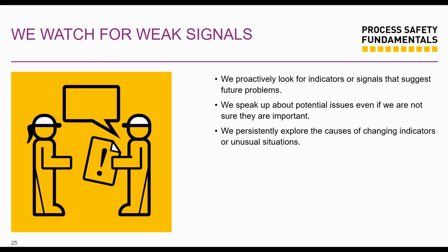So investigate it. Observe small recurring gas alarms. That's another example. You have these gas alarms that keep on going, and you say, oh, it's just a compressor leak, it just leaks, and it's been happening over weeks. Your plant is talking to you. These are weak signals. Don't have it normalized. Make sure that you're constantly checking.